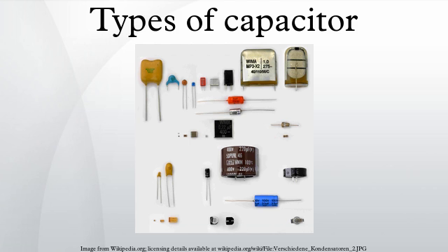Some film capacitors of special shapes and styles are used as capacitors for special applications, including RFI/EMI suppression capacitors for connection to the supply mains, also known as safety capacitors, snubber capacitors for very high surge currents, motor run capacitors, AC capacitors for motor run applications. High pulse current load is the most important feature of film capacitors. So many of the available styles do have special terminations for high currents.